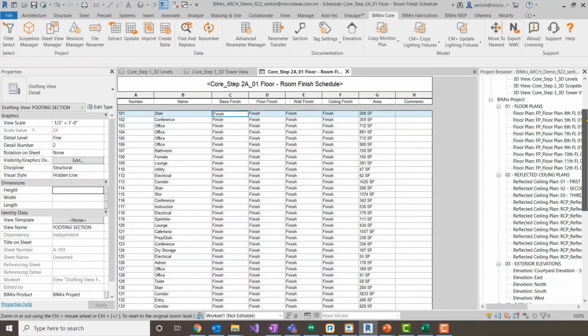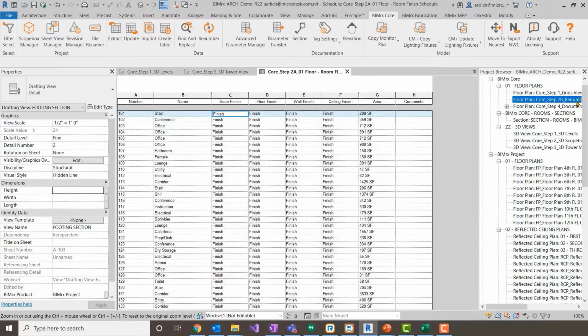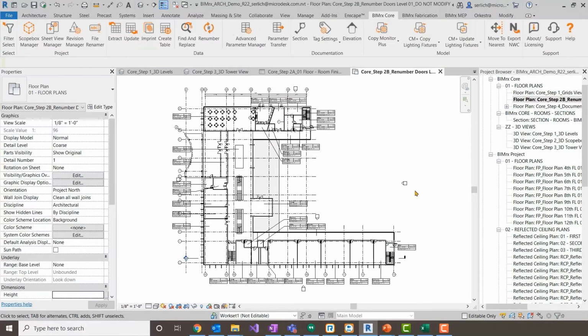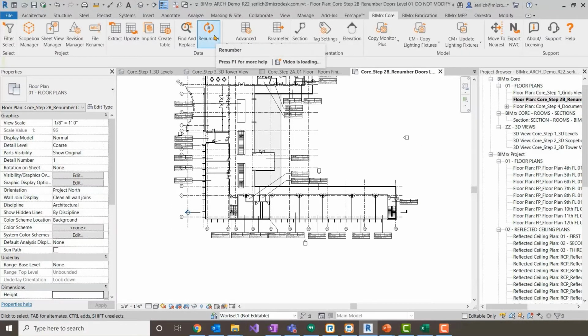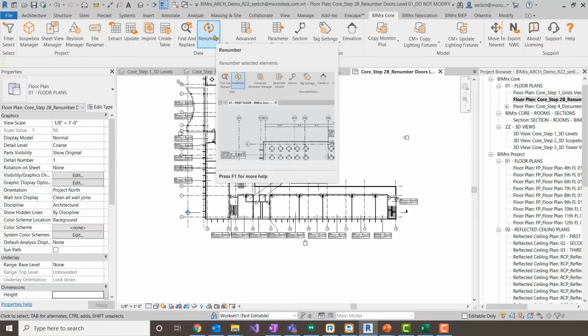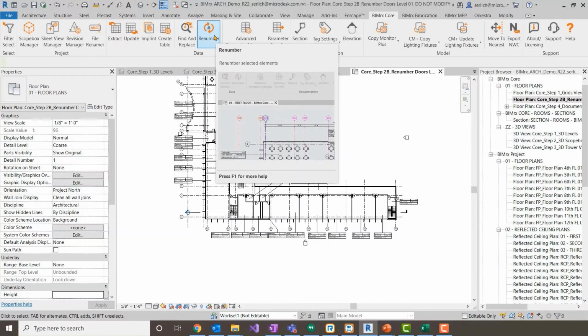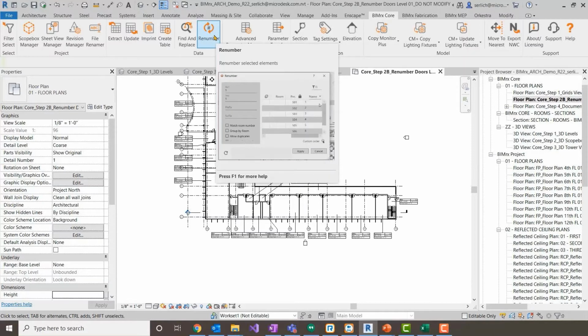And not only are there commands and features that work to update parametric information through Excel, but BIMrx has features and commands that work to update parameters directly within our Revit model. For example, we have our renumbering feature that allows us to renumber just about anything within the Revit model. And this is honestly one of my favorite BIMrx features. As you can see in this tooltip video, the renumbering feature allows us to renumber our grids. And we can even pick on screen the order in which they are renumbered by. Just like that, our grids have been renumbered super fast and super easy.